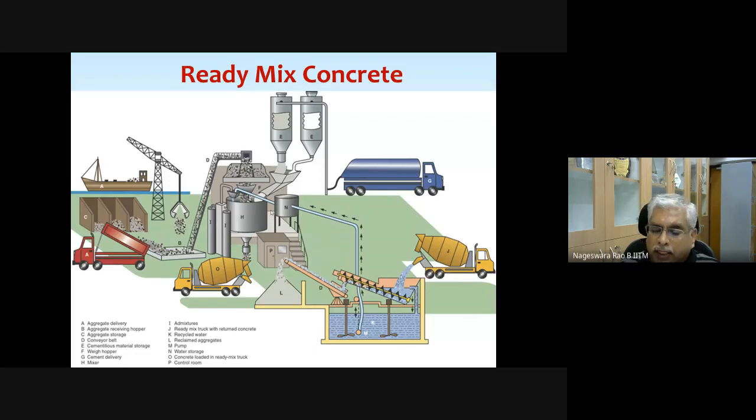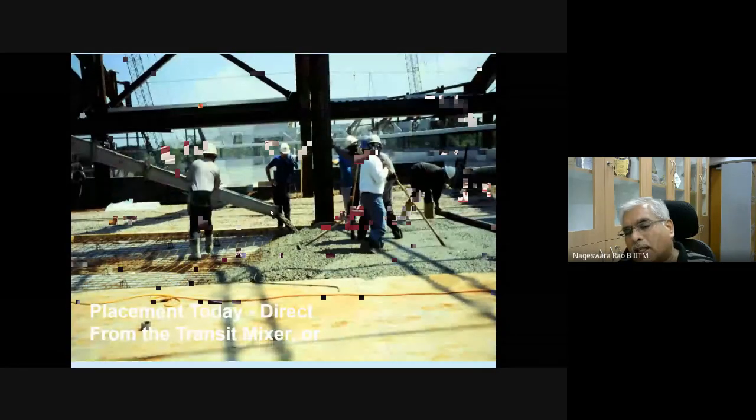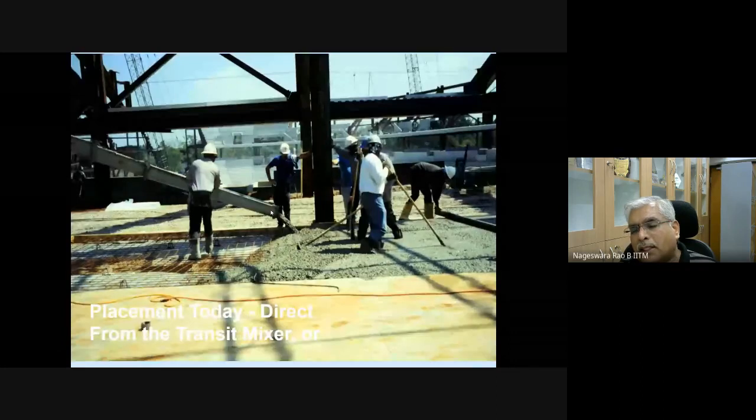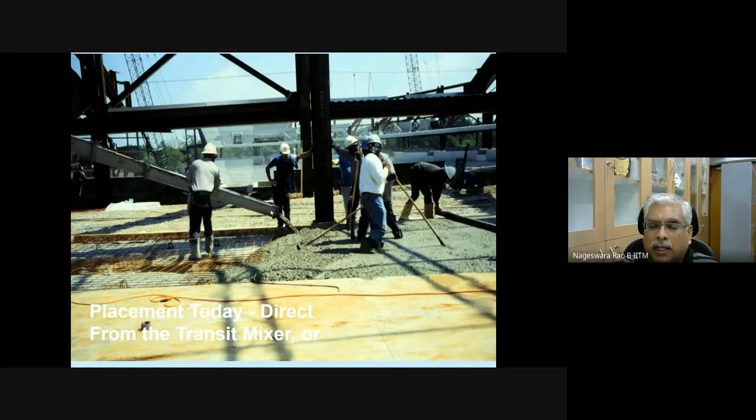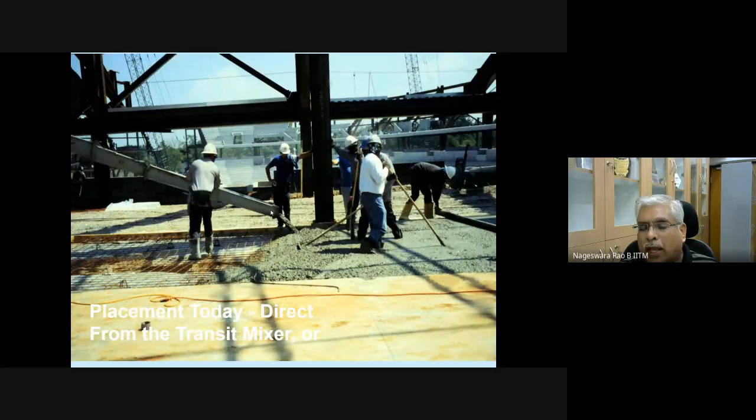Usually, if you happen to visit any of these sites, unskilled laborers like to have it in volume, because they can make a wooden bucket or something like that, and then they put in so many buckets of aggregate, so many buckets of cement, and so many buckets of water. All this will be easy for them if it is volume batching. Okay, so we'll see in detail how to do that.